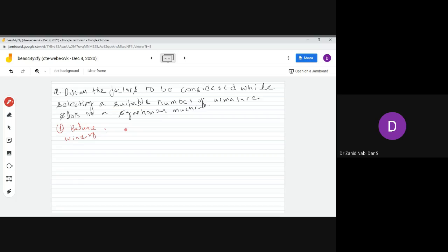Because you have a three-phase machine, you don't have a single phase machine. So R Y B. Last time, similarly, if we are designing a 36-slot winding, for example, in this first slot 1 2 3, 4 5 6, 7 8 9. Suppose here we have 9, again here will be 18, again here we are having 27. So if we are having 27 slots for a three phase winding, we can say it's a balanced winding.